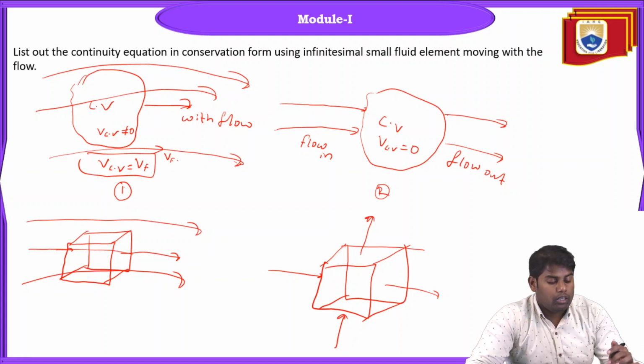In the control volume approach, we see the integral form of the governing equations. Why? Because we perform the analysis for one point and integrate over the control volume, so we integrate over the volume. Then we get the governing equations in integral form.